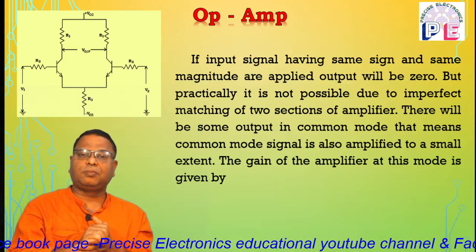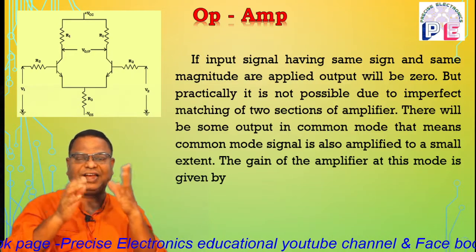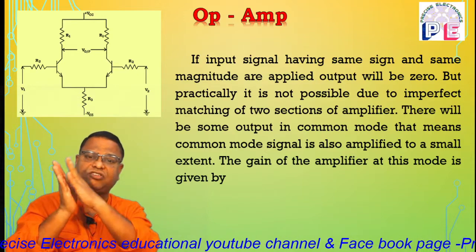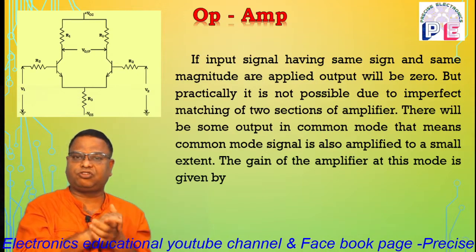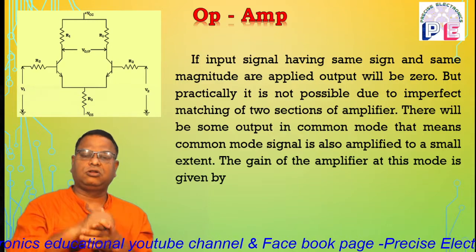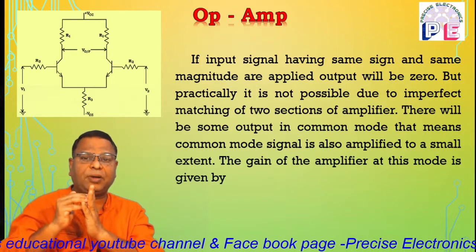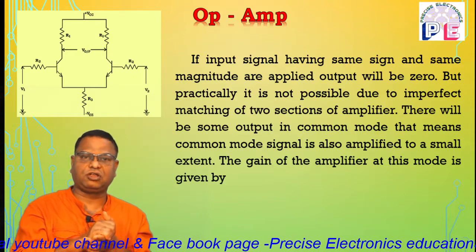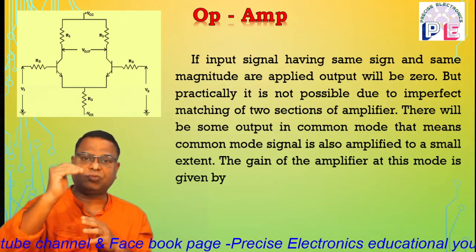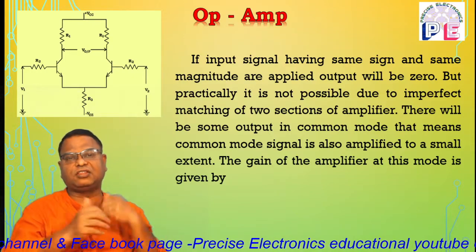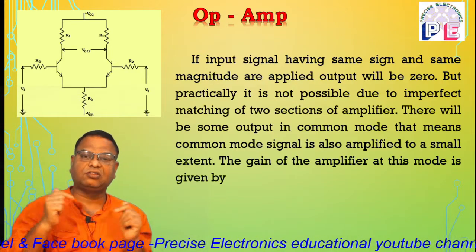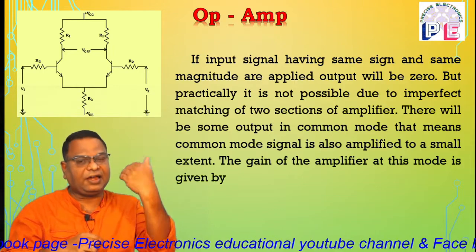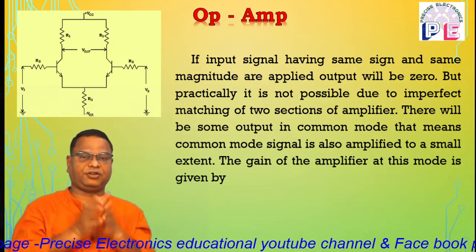As the parameters of transistors are slightly different, if the amplification factor of transistor T1 is more than transistor T2 or vice versa, the transistor having more amplification factor conducts faster than the other transistor, and hence the current flowing through IC1 and IC2 is now different.